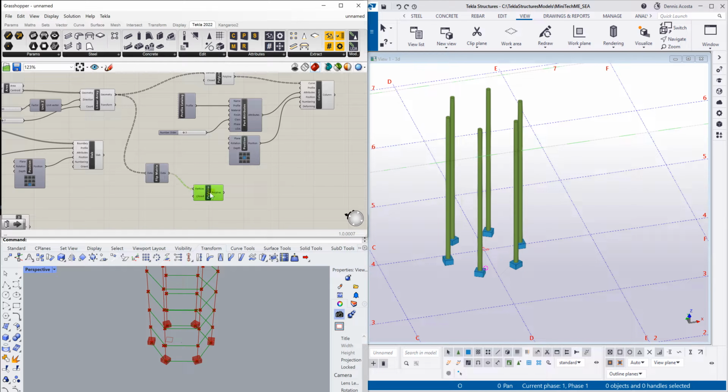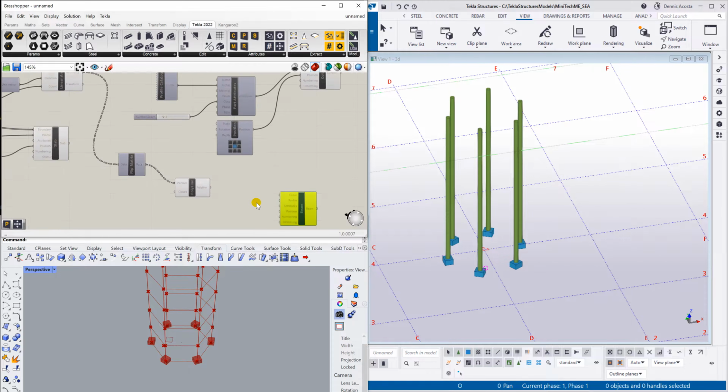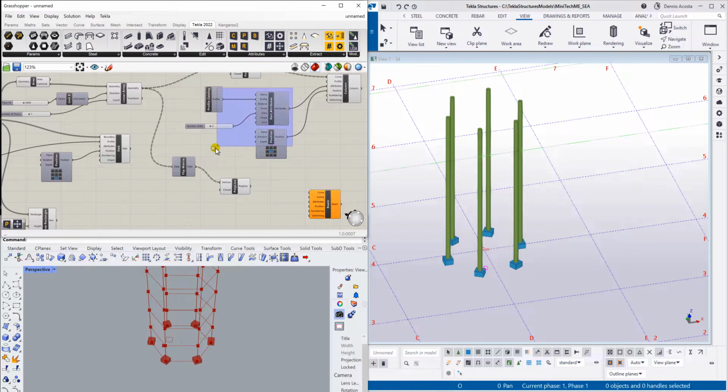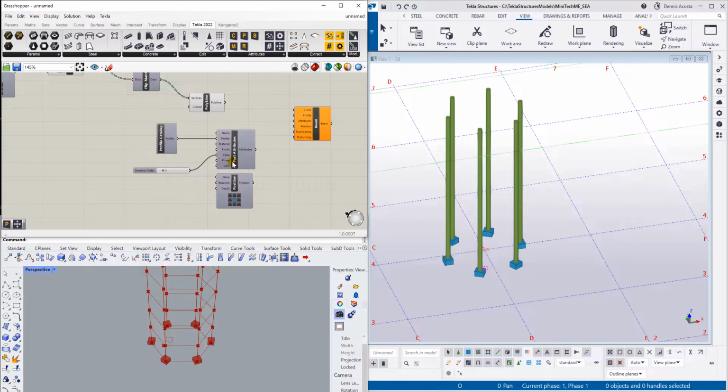Vertices. Okay, and then we can now add the beam. So let's say the beam is something like this one. This is the beam. And again, I can just simply select these attributes. Okay, I will just simply copy that one by selecting the part attribute, by selecting all, and then select one of the attributes and then press the Alt key. It will duplicate.